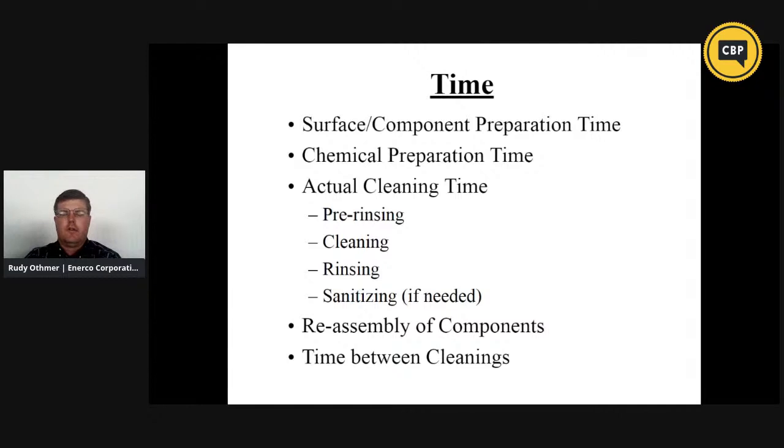So if you're looking at your SOP and you say, okay, I'm going to cycle my acid for 15 minutes, and we all know that's good, but that is not going to take you 15 minutes. You've got filling time with your water.